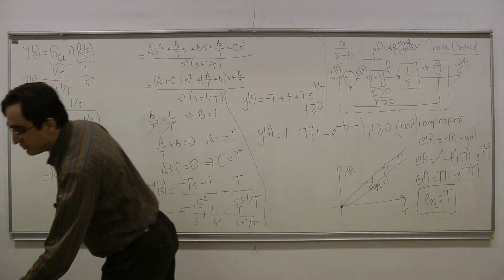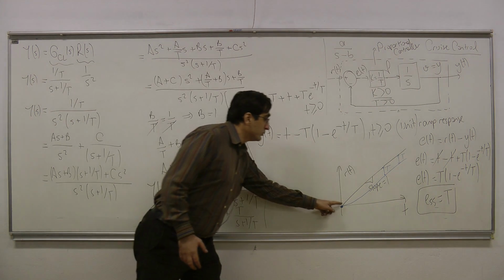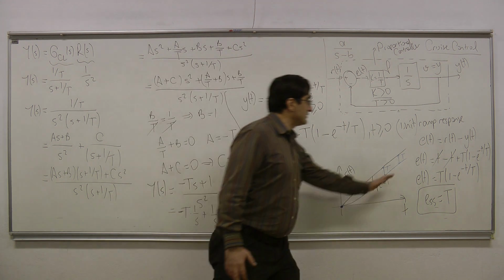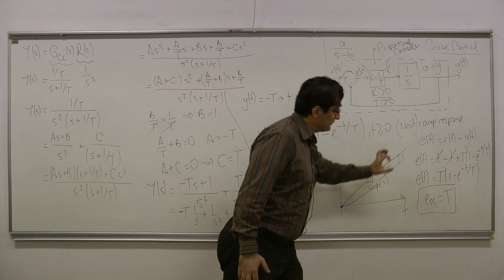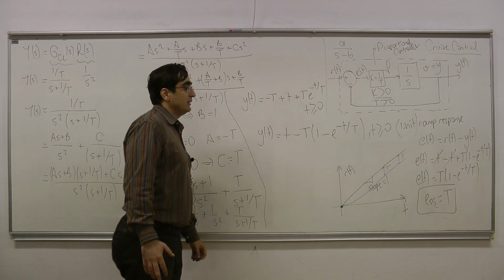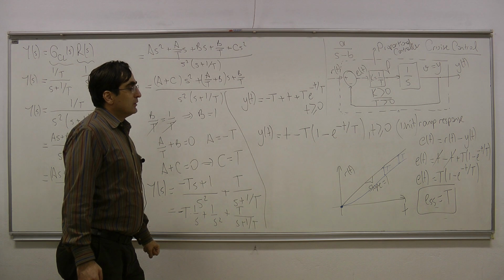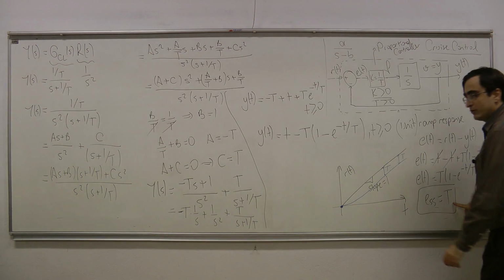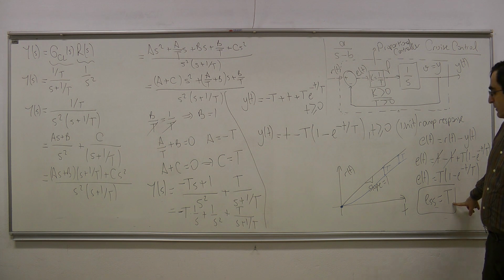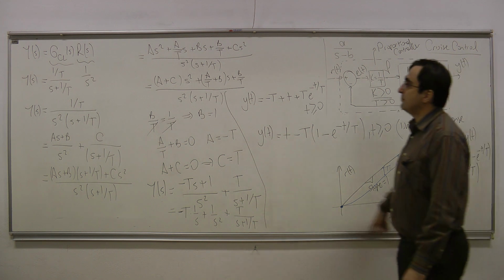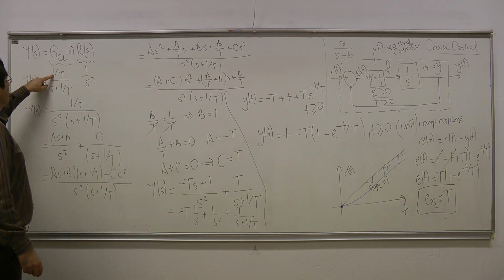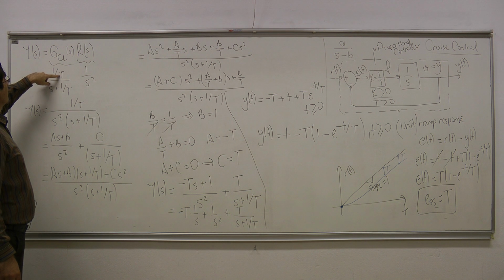In terms of transient performance, this convergence to the asymptotic behavior, and in terms of steady state performance, this difference, we need to make T smaller. So here you see again that this T is actually a Laplace domain quantity. It's a parameter of the Laplace transformation. Okay? So it is a parameter of the closed loop transfer function. This capital T is such a parameter.